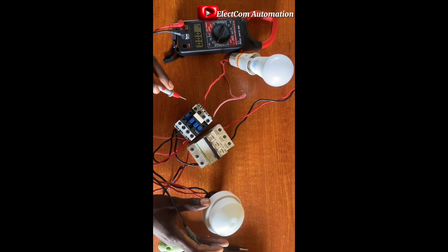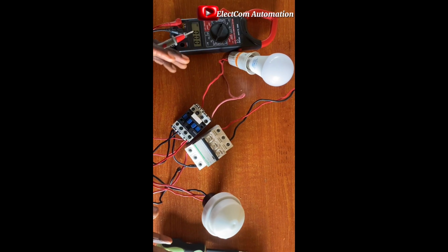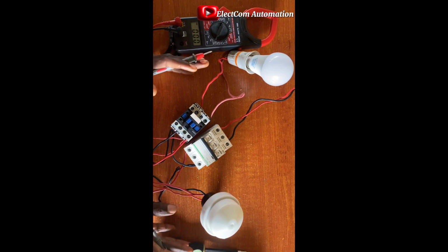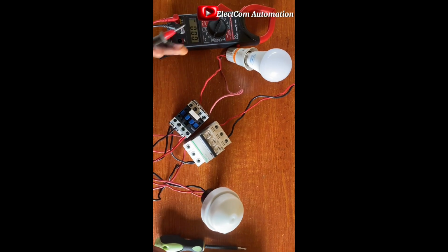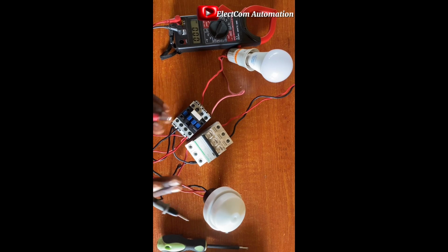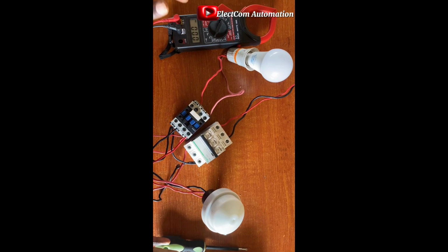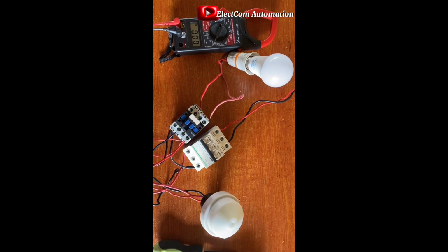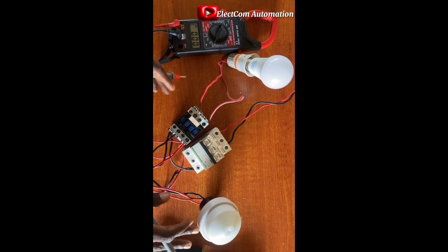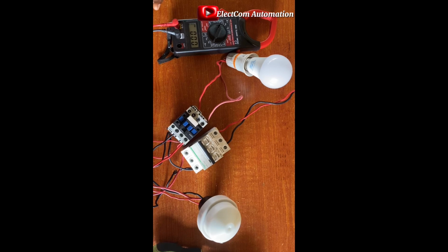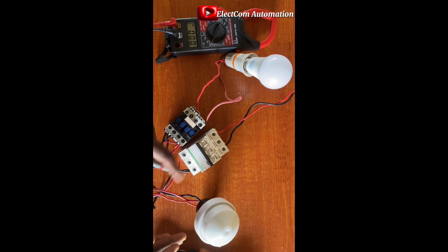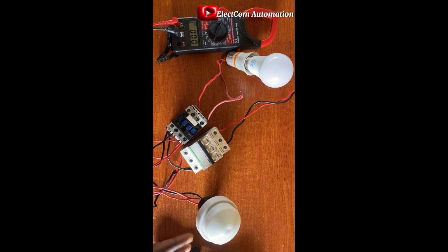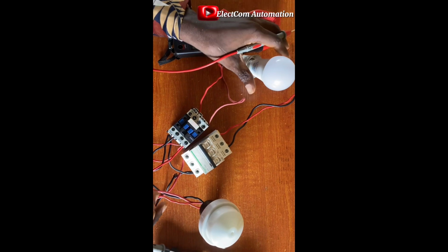And this is my photocell. Now how the system operates is that at night the system will automatically switch on, and at daytime the system will automatically switch off. Now it is daytime because there is light intensity radiating to the photocell. If I bring any black object, making the environment of the photocell dark, it means it's night, and it will switch on the bulb.